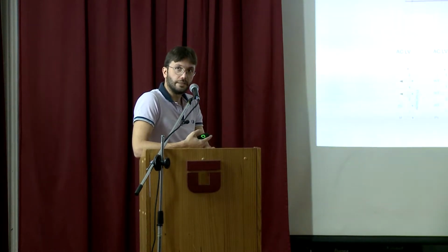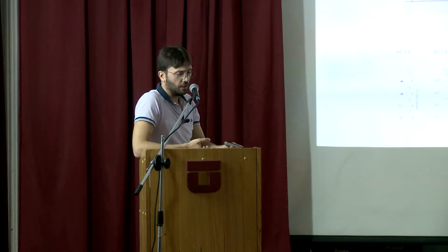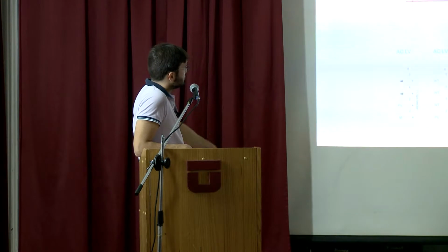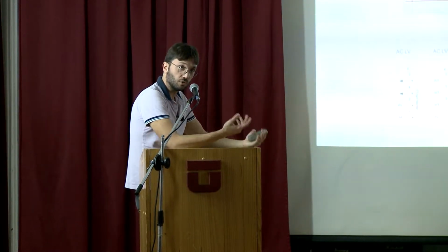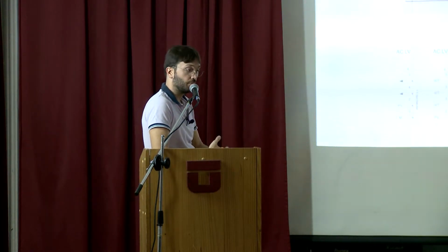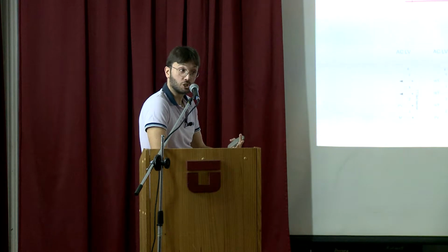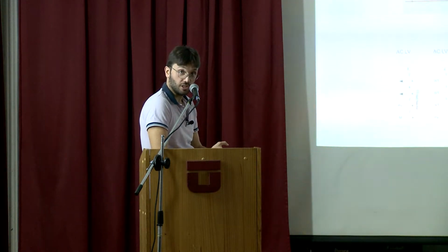If you want this to happen, then you need to have reactive power compensation. But for a current controlled converter, this comes for free. Then, of course, power quality: you can compensate for the harmonics into the grid. You can really do a lot once you have completely controllable power electronics connected to the grid. There are so many areas you connect.